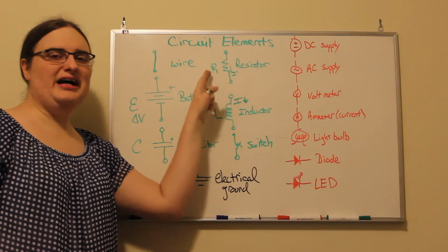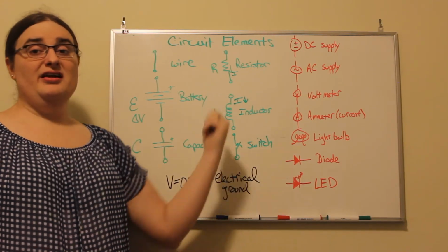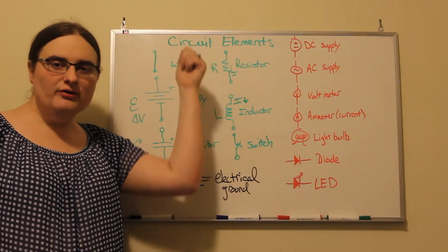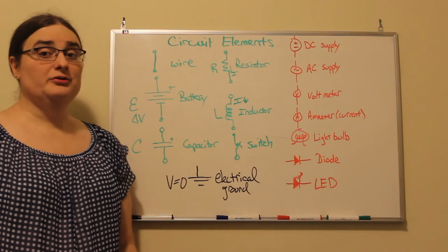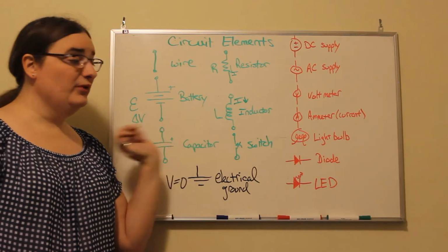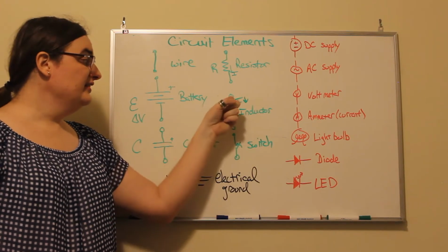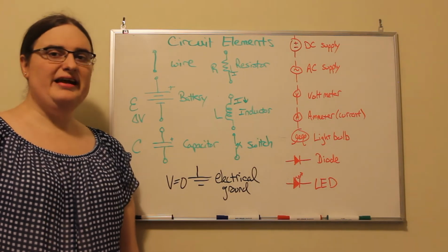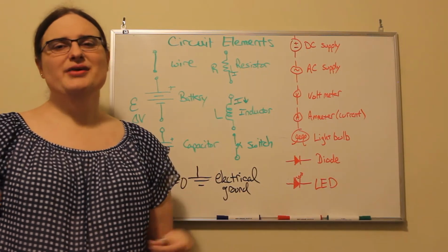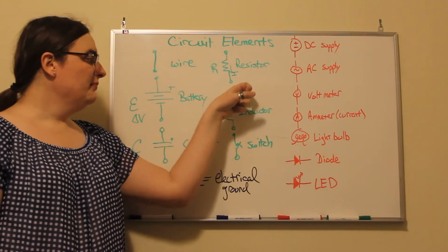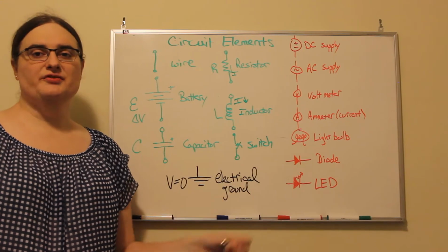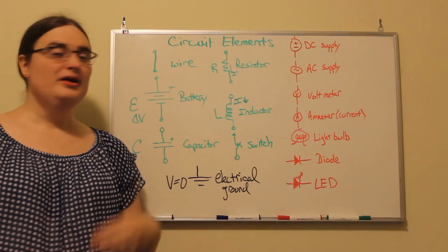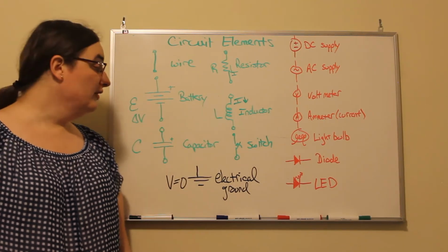You can think about a resistor as being like a slide. If a battery is a ladder, then going with the normal flow of traffic, you're going down a level. Against the flow of traffic, you're going up a level. The last circuit element we commonly use is the inductor. An inductor looks like a little solenoid, a little coil. It'll be labeled with an L, and sometimes you'll see the direction of current noted, because as you go through an inductor with the direction of current, there would be a reduction in the electric potential difference based on the EMF of that inductor.